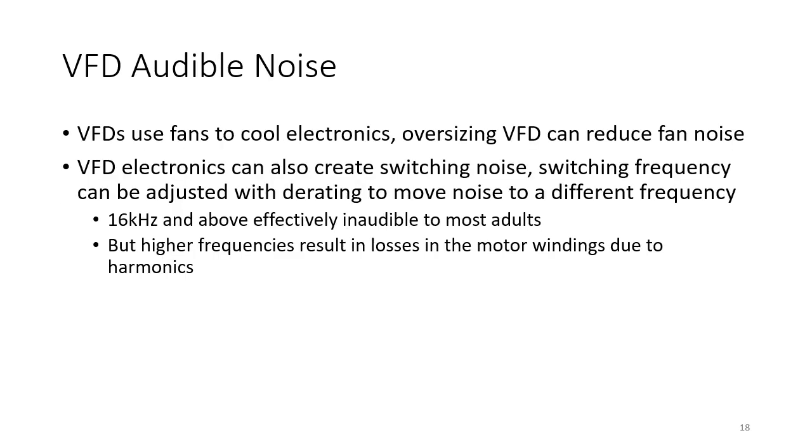Now, I mentioned audible noise coming from variable frequency drives. Variable frequency drives often use fans to cool the electronics. Those fans can be quite noisy, particularly as the VFD gets hot and the fan has to run at full speed. So one possibility there is if you oversize a VFD, then it doesn't get so hot. So that can reduce fan noise because you don't need to use the fan so much to cool it down. Of course, it costs more because you're choosing a bigger VFD. It reduces your efficiency somewhat, so your energy savings aren't quite as good, although that's less of an issue. But it's certainly very good where audible noise is important, particularly around the fan speed.